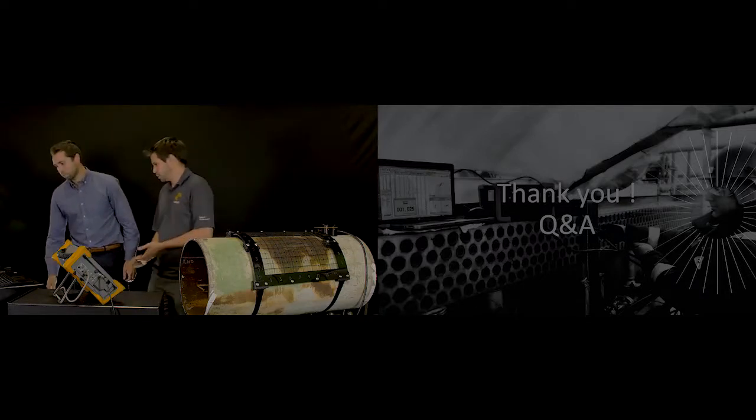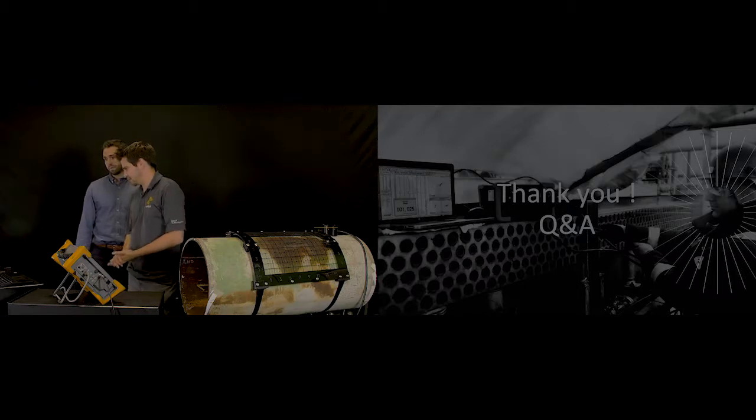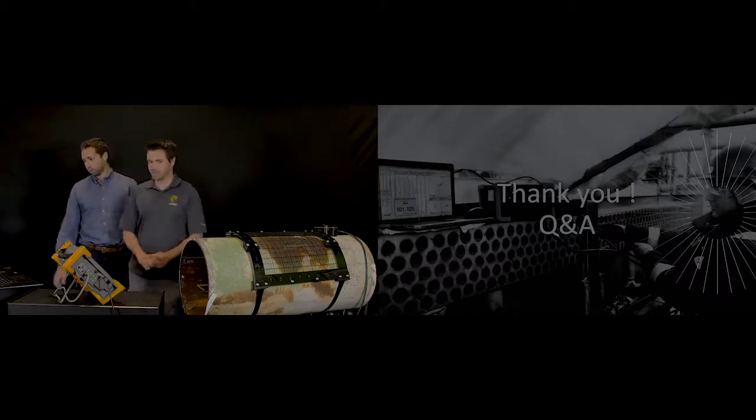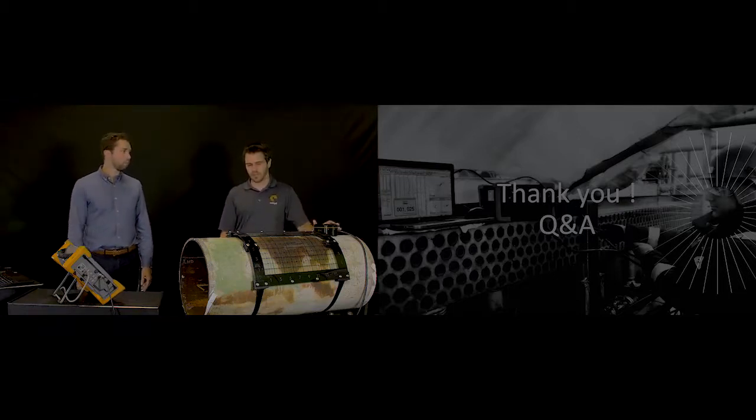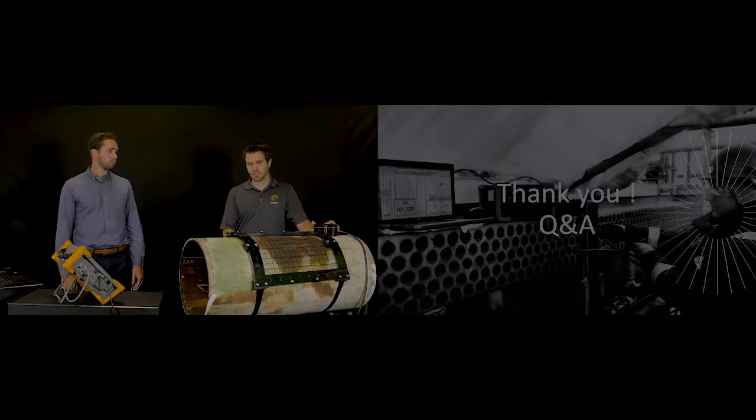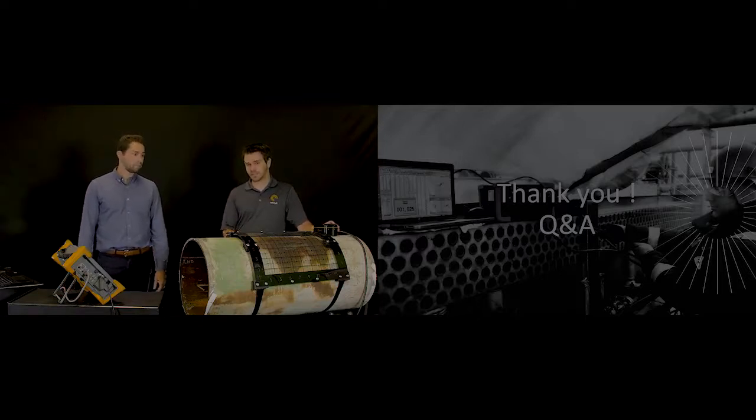And someone is asking us, is there any advantage to use this probe versus EMAT to inspect scab? Well, there's a few advantages in using this probe. The first one is that you will be able to size deeper flaws. EMAT is going to be somewhat limited, whereas the PEC system is going to allow you to size flaws that are down to 15 to 20% remaining wall thickness. So you're really going to be able to assess the extent of the damage, even if it's very deep.